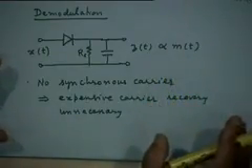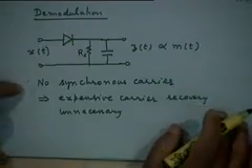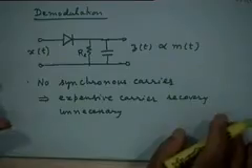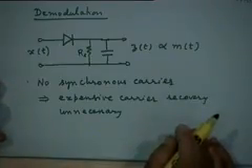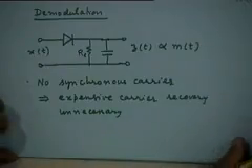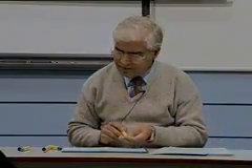And if this works, as we indicated briefly how it could, the advantages of this simple circuit are that we don't require any complex circuits for synchronization of the local carrier with the incoming carrier. So no synchronous carrier is required, and thereby the receiver becomes a much cheaper version. Now this was a very brief introduction to how the demodulator works.